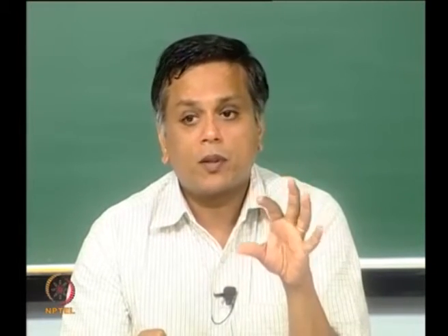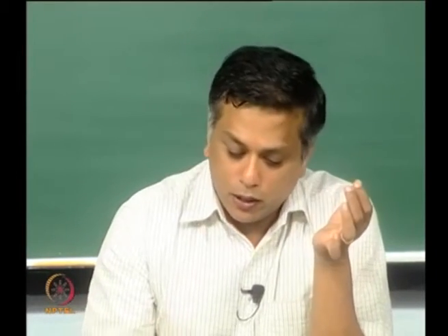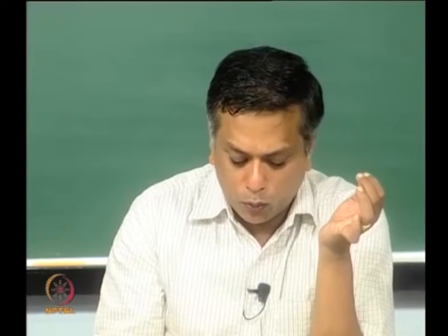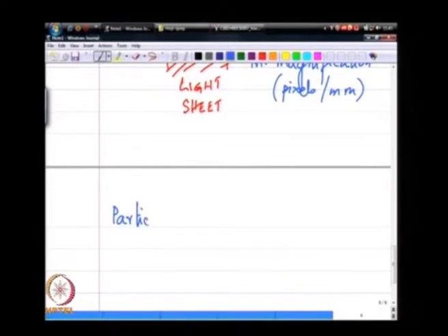These are large drops that I can mark. Except when that happens, most of the spray is going to look like a grayscale image with little dots, and I need to get velocity information from that. To do that, we have to move to a technique called particle imaging velocimetry.